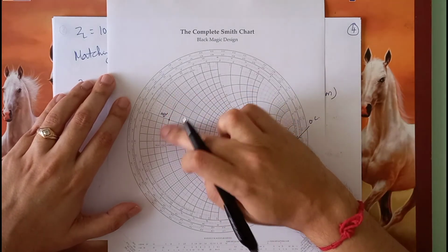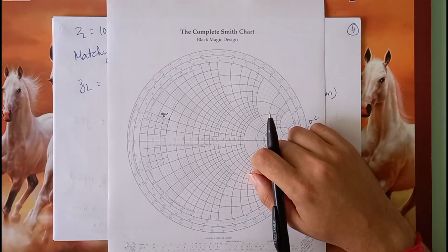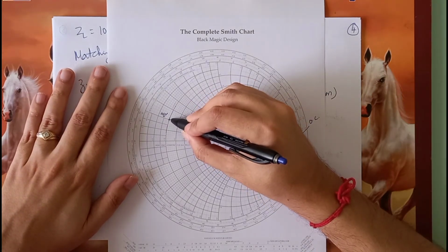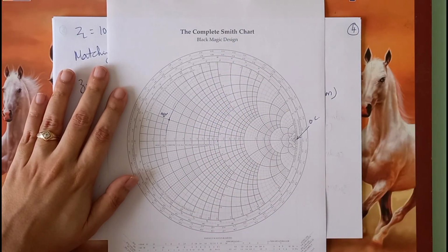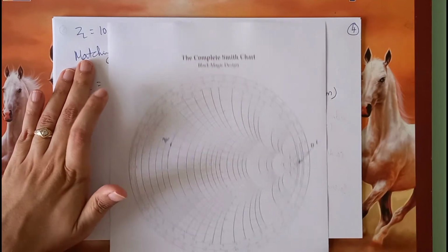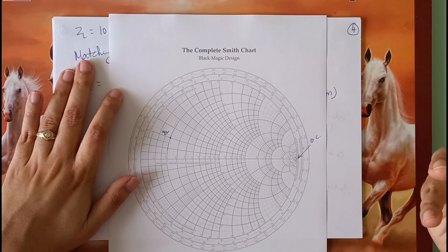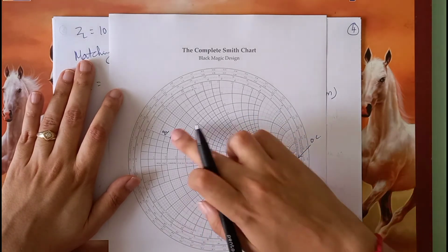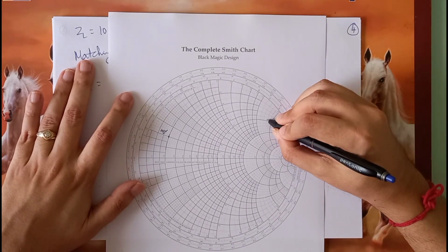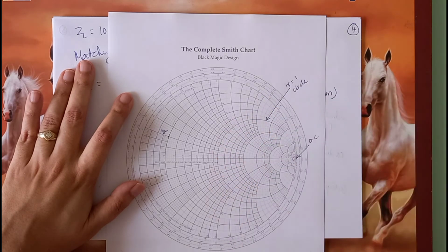Well, one thing is for sure. We have to move on this circle. We cannot move on the inductance circle. We have to move on the resistance circle, because at least we don't want to add any more lossy elements. Right? So the point is, whether we are moving up or moving down, we don't know which is the right place to stop. Because what was our initial goal? We were trying to ensure that somehow we can make the resistance component 1. But the resistance component 1 is on this circle, and we can never ever reach this. Because the only place where we are meeting is the open circuit point, and that is of no use, because it's not really meeting, it is just touching. So somehow we have to figure out a way to come to this circle. So now this circle is what we call the R equal to 1 circle, or the constant resistance circle of value 1.